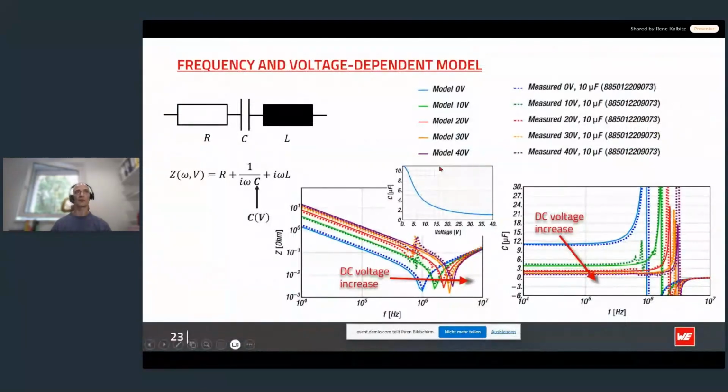The LTspice model is based on the typical RC model then, which also takes voltage-dependent capacitance into account. This approach does, at the end, not only model the voltage dependence, but it describes the frequency dependence as well, as is shown here in the capacitance and impedance spectra.